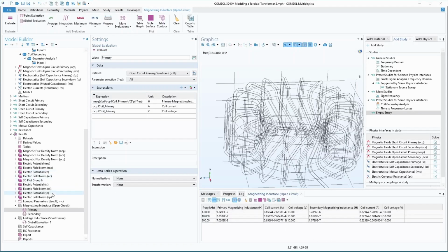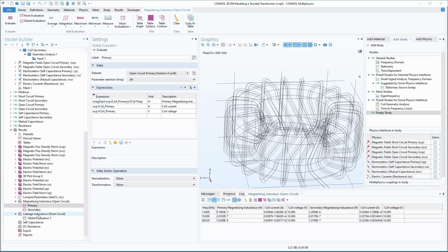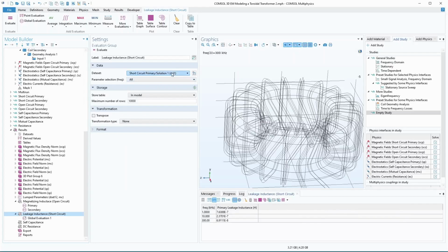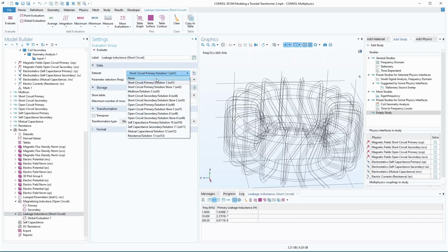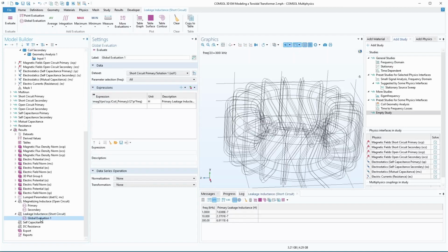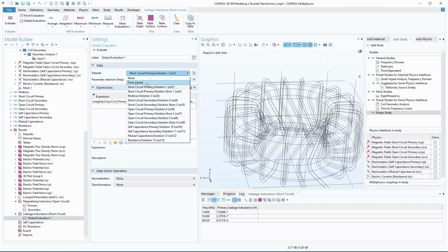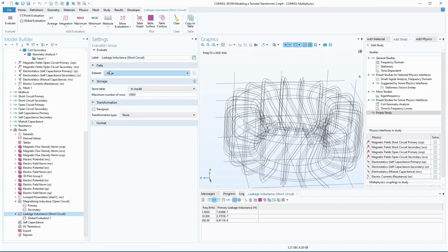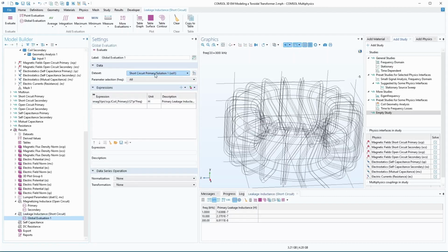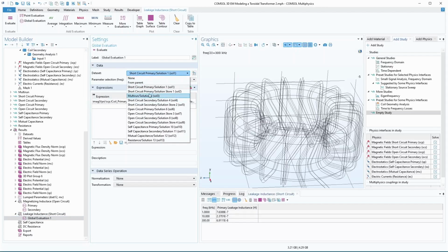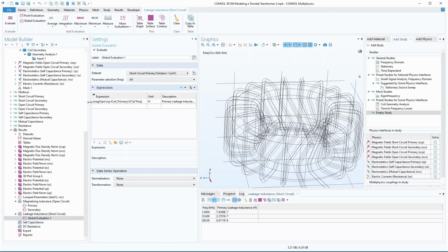Well, I'm just going to finish filling out these different formulas here before I try and troubleshoot what's going on with the inductance. So the next one here is the leakage inductance. If you're doing these here not all linked from parent, then might as well make the parent just none. So I'm going to make this one here the short circuit primary. So we have that, and it's the same formula here for the inductance. It's just different now because it's the short circuit test.